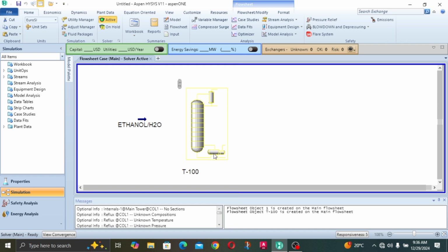So at the bottom, like we had in our schematics, we have a reboiler. The reboiler does the reboiling effect of boiling the liquids at the bottom. The liquids at the bottom of the column would still be a mixture of ethanol and H2O, but the reboiler does a little bit of reboiling to vaporize one of the two components, so that it can go up and have a more efficient separation. It's a loop, a continuous process. Basically, it continues doing that until we have an efficient separation between the two components.